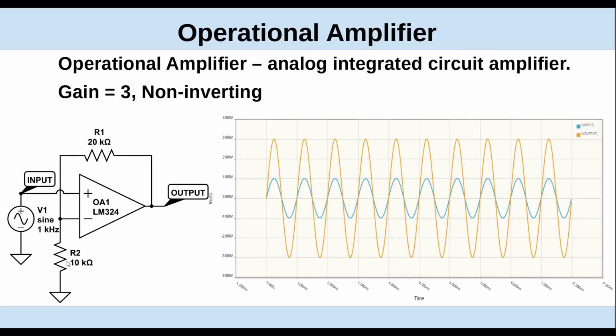Okay. 20 and 10 is 30 ohms, and we're at 10 ohms. So we're 1/3 of the divider. So if I've got 1 volt coming in here on the input, when this output gets up to 3 volts, I'll have 1 volt on this side and they'll be balanced again.